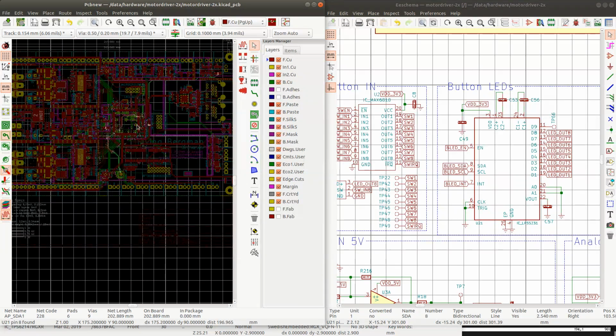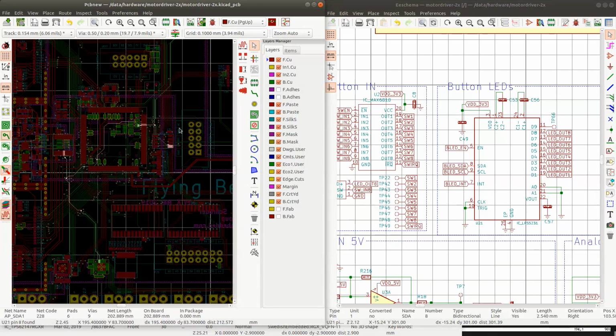Yeah, there is quite a long wire, which had to be this long for the I2C. And it could actually be that there is interference that causes I2C to fail.